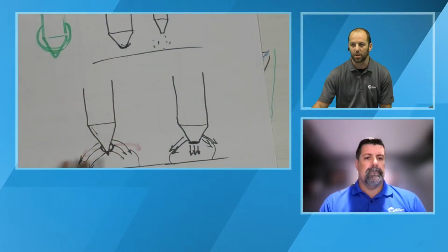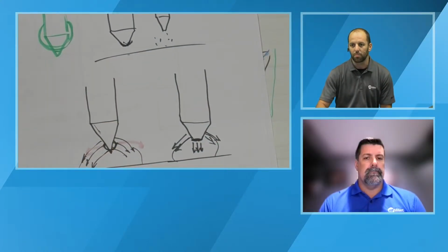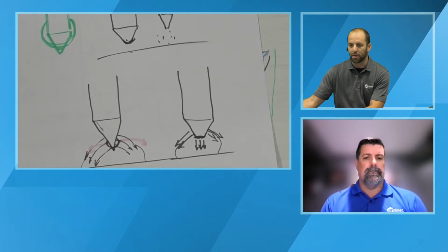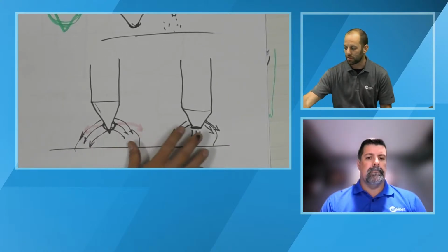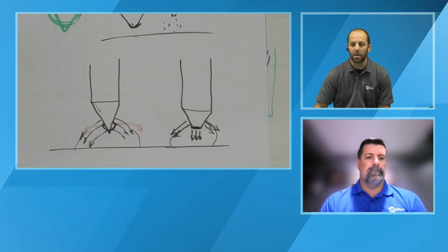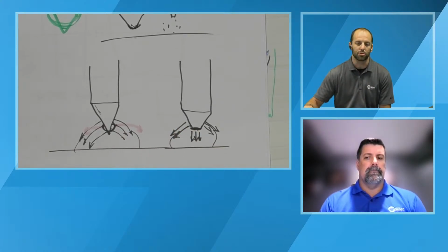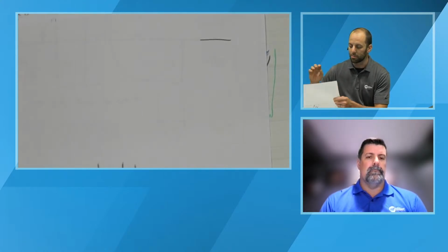That can benefit anybody welding aluminum, because in the AC waveform we tend to have a little bit of arc wander. Using these things in conjunction with each other, you can help focus the arc better underneath where the torch is pointed, and that helps the operator accomplish the weld a little bit easier.